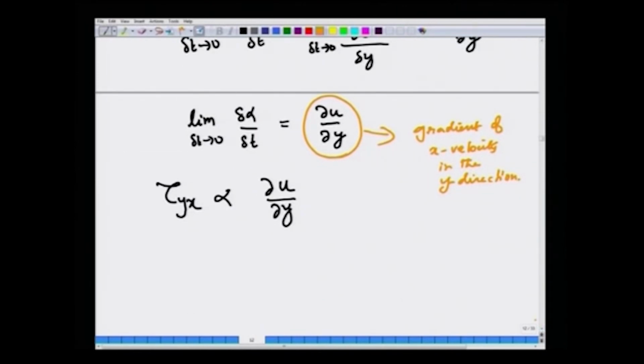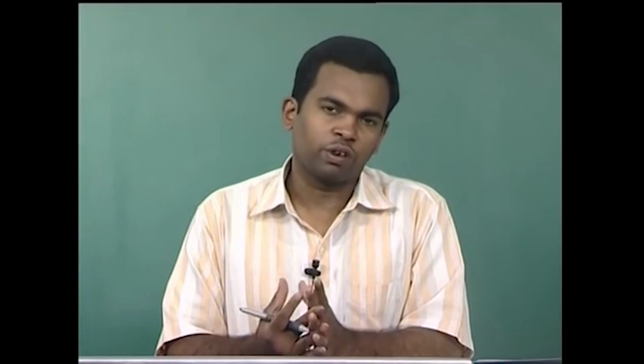So, in a fluid, in a liquid or a gas, the amount of stress that you exert will not be proportional to the deformation itself, it will be proportional to the rate of deformation. In simple words, a fluid does not care how much you deform, rather it cares about how fast you deform, while a solid merely cares about how much you deform, because in an elastic solid, the stress is directly proportional to the strain, the amount of deformation, whereas in a fluid, the stresses are proportional to the rate at which you deform the fluid. So, if you deform the fluid quickly, the stresses generated will be more, while if you deform the fluid more slowly, the stresses generated will be less.